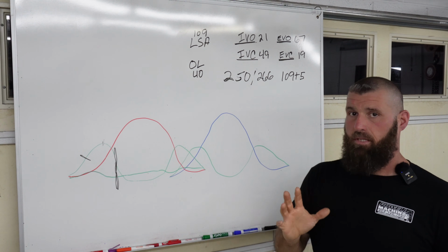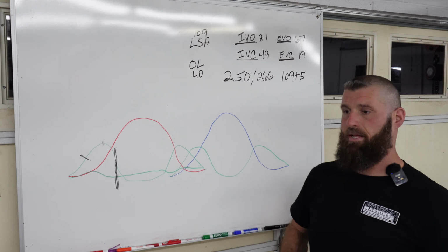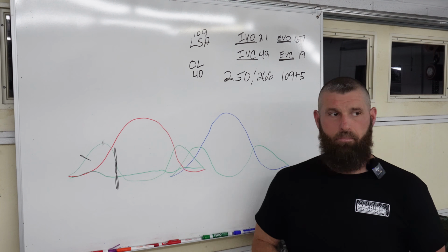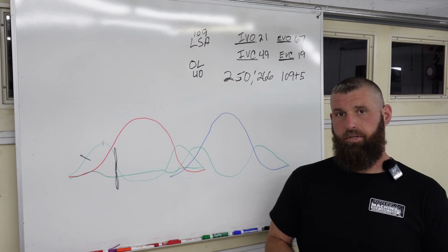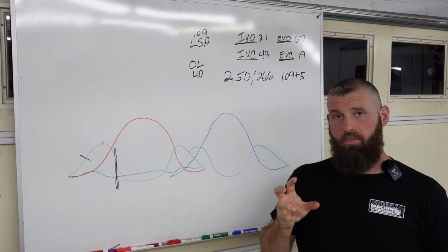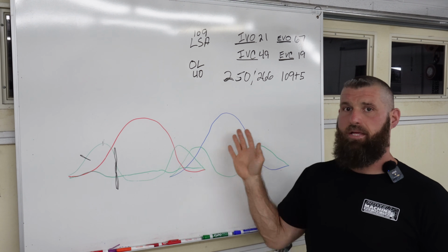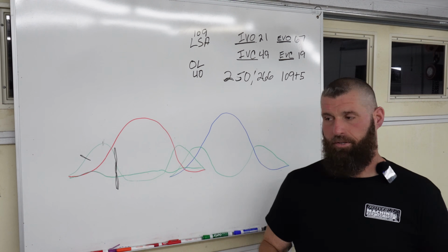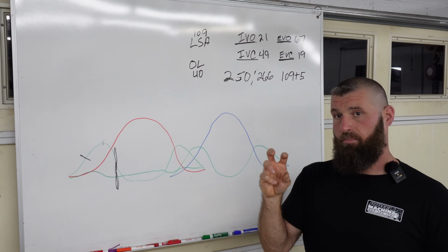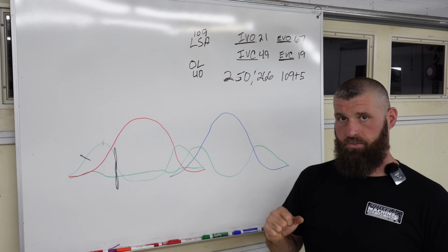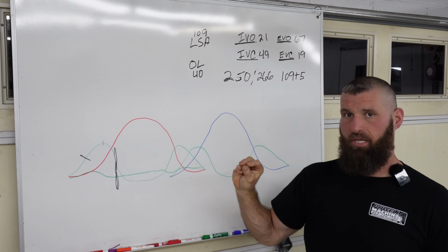People like to calculate dynamic compression, you know, I got this dynamic compression or I got that dynamic compression. The problem with dynamic compression is you don't know the answer. Like, well, I got a calculator. Well, no, you don't. The problem with dynamic compression is volumetric efficiency is not in the calculation. Why does that matter? Volumetric efficiency is going to determine how much the cylinder fills, regardless of your dynamic calculation.